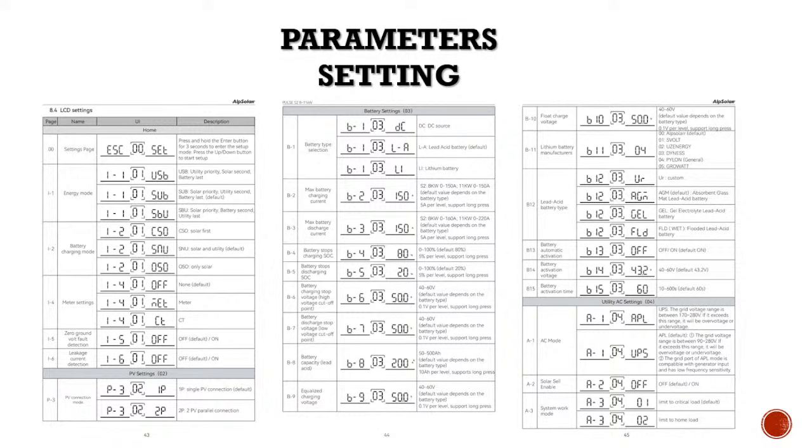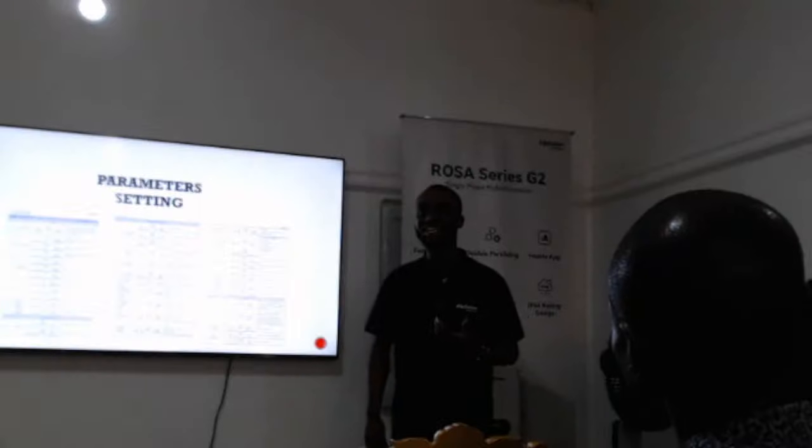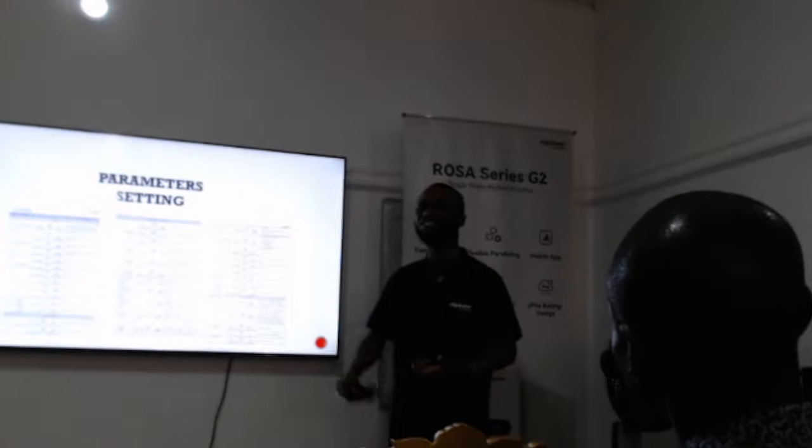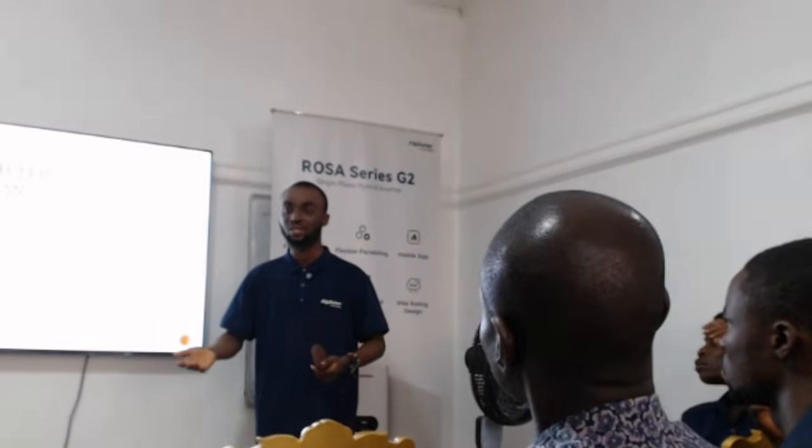This inverter has an internal BMS that can equalize charge. There's something they call equalizing charging. Equalizing charging is an intermittent charging. You charge your lead acid battery to ensure that the chemistry of the batteries is properly mixed together. Sometimes, once you have used your battery for a while, the chemistry inside will settle down.